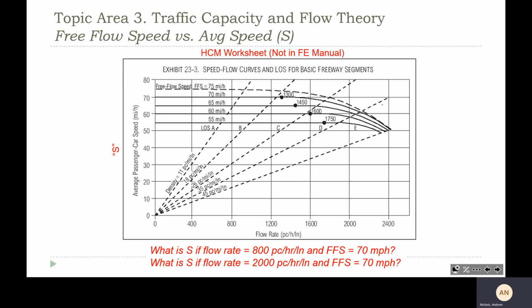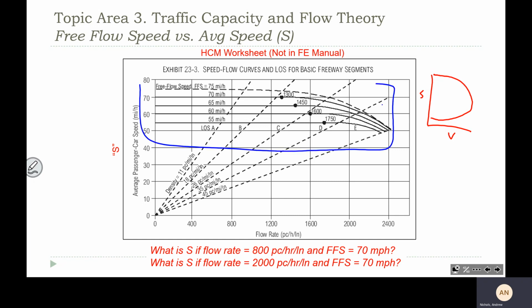Yeah, so here it is zoomed in. So jumping back to the Greenshields model, we had speed and flow rate. So speed and flow rate from that Greenshields model looked like this. As the cars increase, the speed is going to be impacted until you get to a max. So what you're seeing here is only this portion of that curve. That's why it kind of tails off.